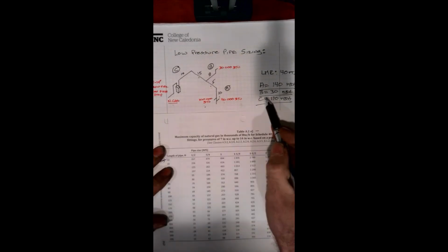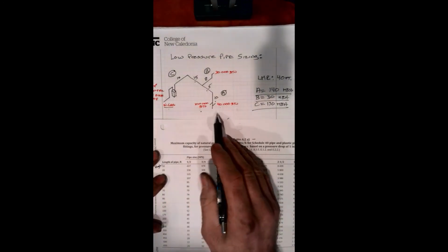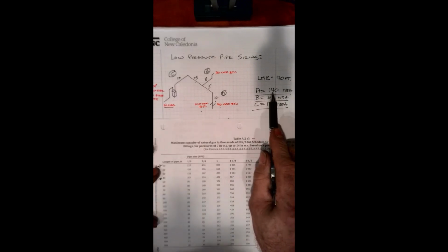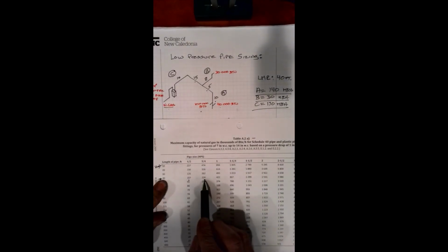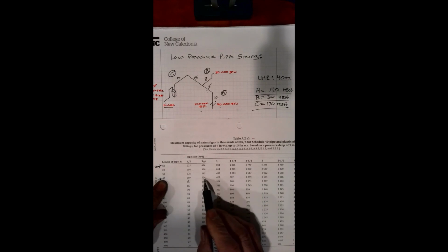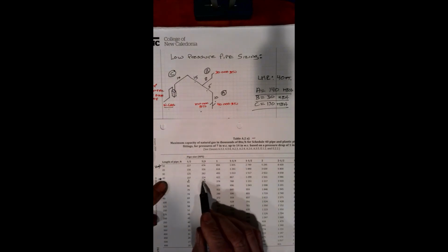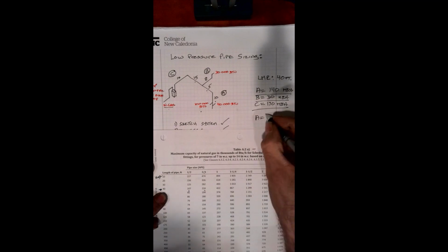Okay, so now we'll revert back up to our measurements. So working backwards from the longest measured run, we'll start with A. We need 140,000. So we'll go to our 40 code zone. We're going to move over to here. Now these are in thousands of BTU. So we need 140, but half-inch pipe is only going to supply 107,000 BTU. So we can't use that pipe. We need to go up. 3/4 inch pipe will serve up to 224,000. We need 140, so this would be a good choice for our supply pipe. So pipe A would be 3/4 inch pipe.